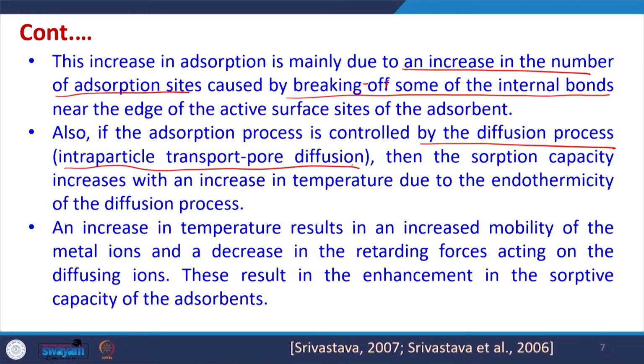Also, if the adsorption process is controlled by the diffusion process, that means intraparticle transport or pore diffusion is controlling, under that condition the adsorption capacity may increase with an increase in temperature, because the overall diffusion processes are endothermic in nature. So, if adsorption is diffusion controlled, the overall process may become endothermic, because diffusion increases with increase in temperature.